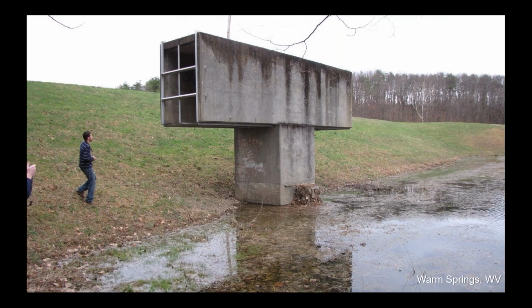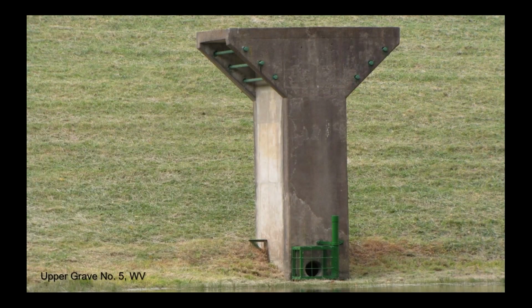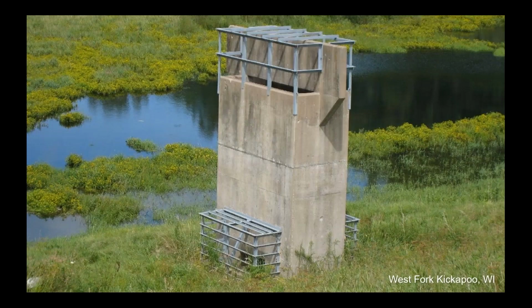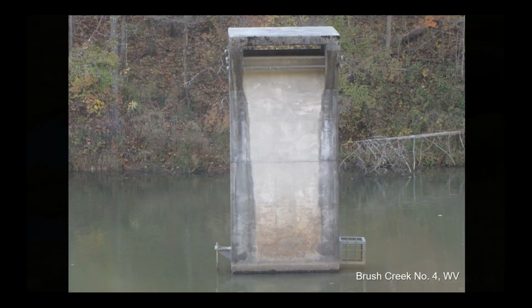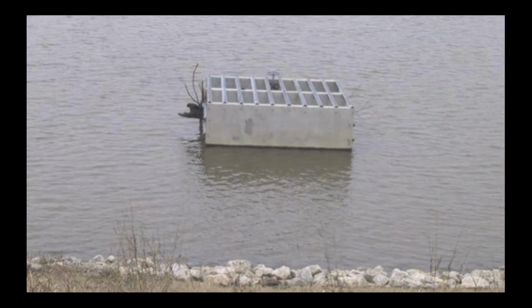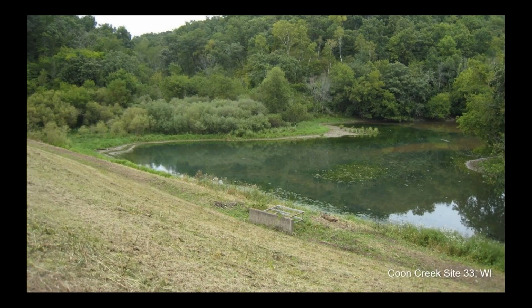Here's an example of one in West Virginia and another one, and you can see they're all variations of the same thing. They just have slightly different configurations, sometimes inlets at different levels, but they are all serving the same primary purpose, to act as the principal spillway. And for flood control projects, you sometimes have multiple inlets to address different flood control needs. But I just want to show that there are different layouts and different configurations of the same type of riser structure. They're not always in the reservoir.